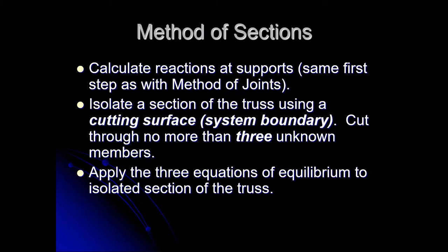And the sum of moments about a point equals 0. So we can apply those 3 equations to the isolated section of the truss, and in solving that, we will end up with our unknown stresses or our unknown forces. So we solve for our unknown forces.